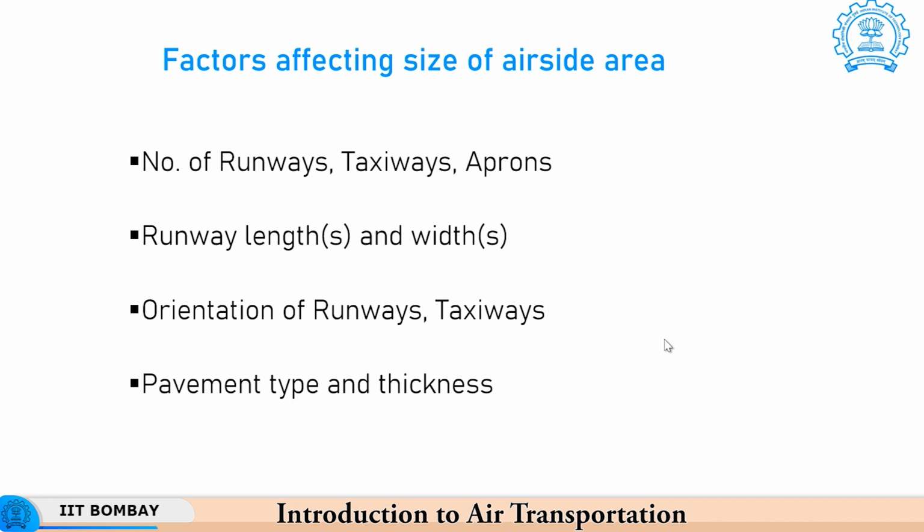And also the pavement's type and thickness, because as the aircraft become heavier, you need to have a thicker pavement to take the load, and there are two types of pavements. There is a flexible pavement and then there is a rigid pavement.